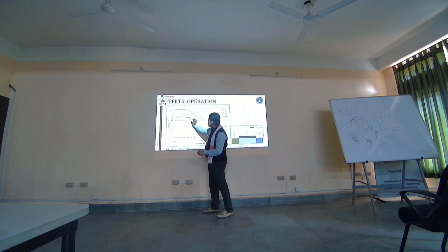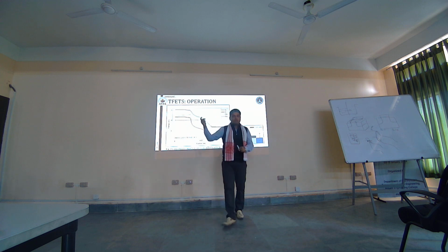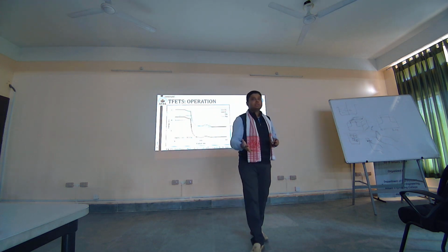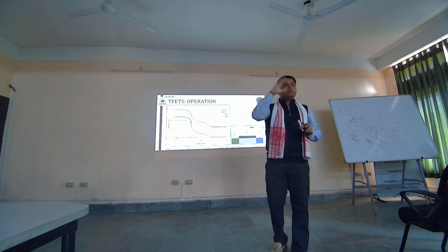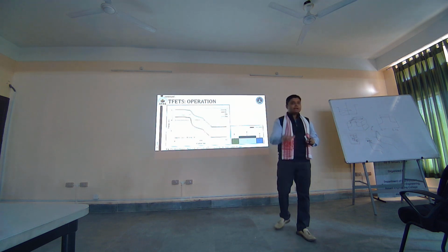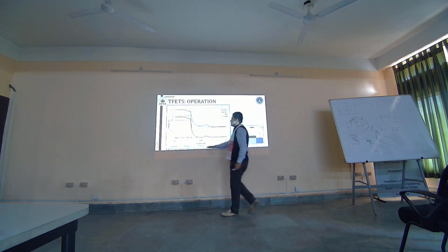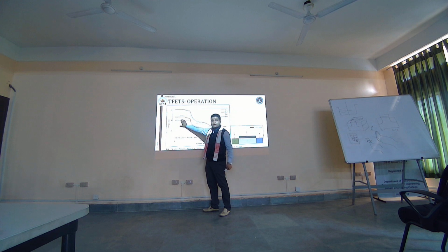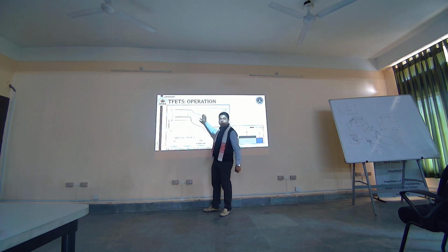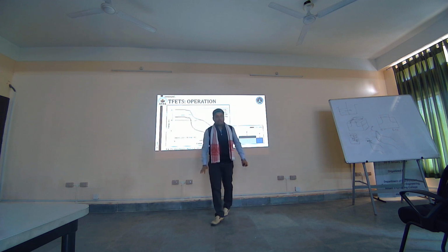So at a very high voltage, you see this particular region constricts. This length becomes very small, so basically the tunnel width reduces. Under that condition, you can have minority carriers from the P plus source move to the channel by the action of quantum mechanical tunneling. But